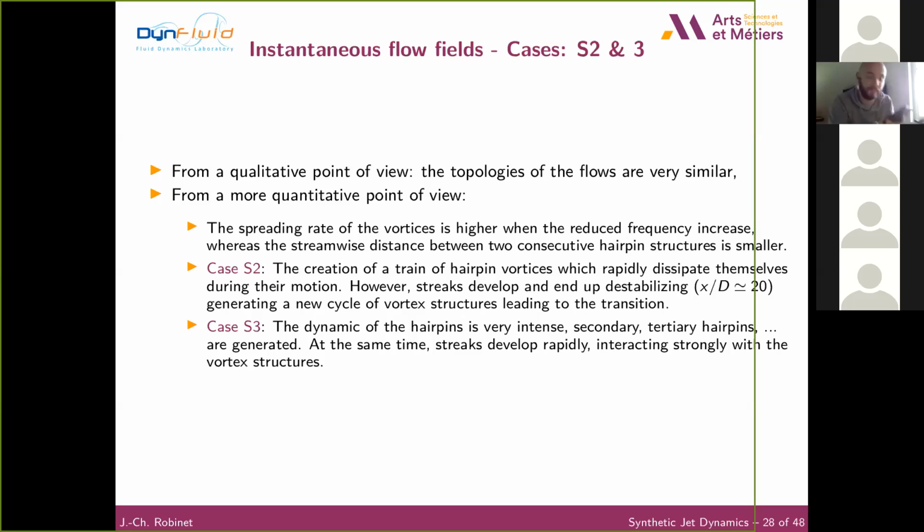I recall it's necessary to have three elements. Shear flow, okay, is not modified. Oscillation is modified by the frequency, and contra-rotating vortex is also modified by the frequency. And in fact, the last two are not optimal to generate hairpins in such a case. It's exactly the inverse for case 3. In case 3, the contra-rotating vortex is more intense, and the oscillation permits generating hairpins easily.